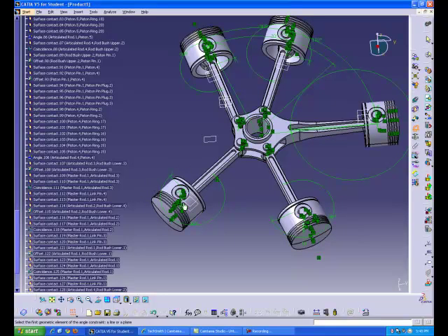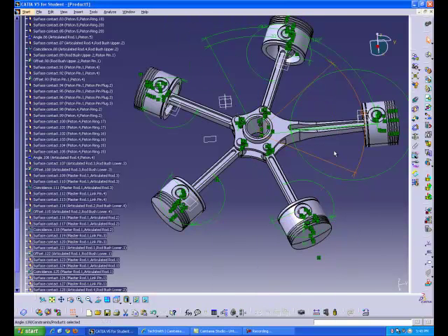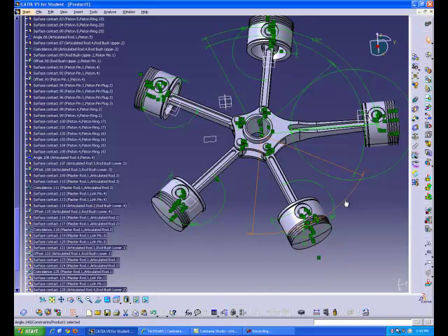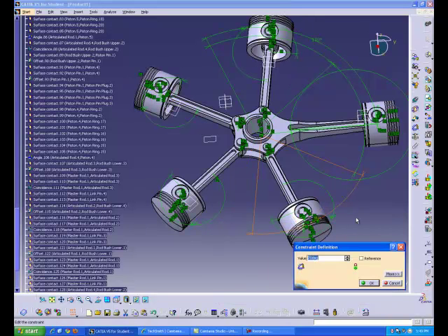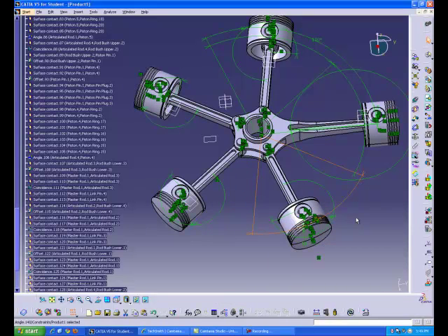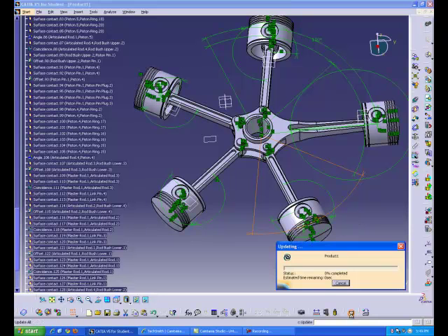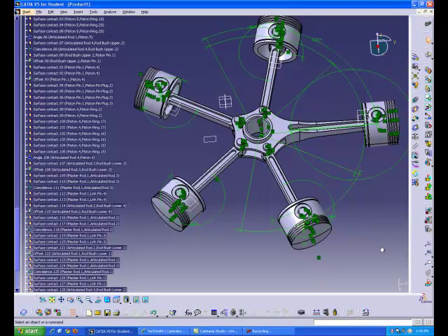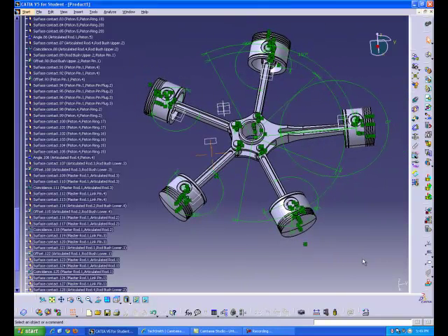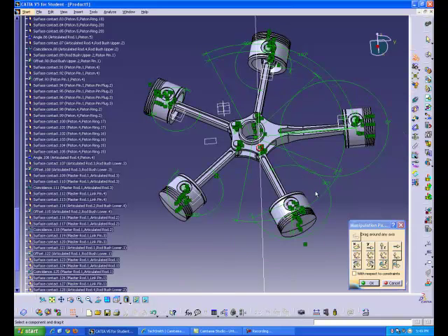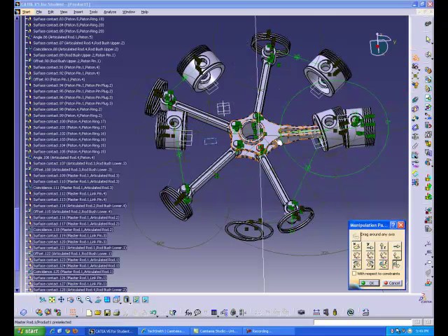And now repeat this twice for the next two pistons. We don't have to do the last piston and the piston connected to the master rod because that will just over constrain it and it's not needed.